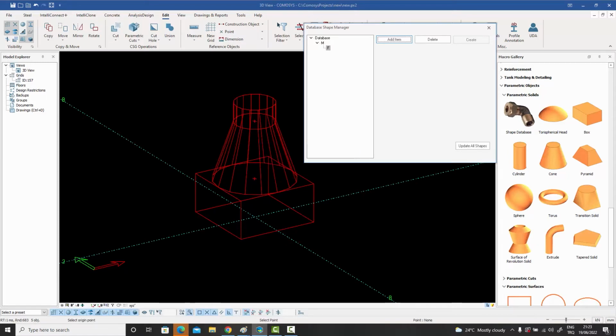And when I do that, since I've already selected it, it directly goes on to ask me for the select origin point. If I hadn't selected it, it would have first asked me to select the objects. But since I entered the command with something selected already, it directly goes to the select origin point. So I'm going to select this as the origin point.